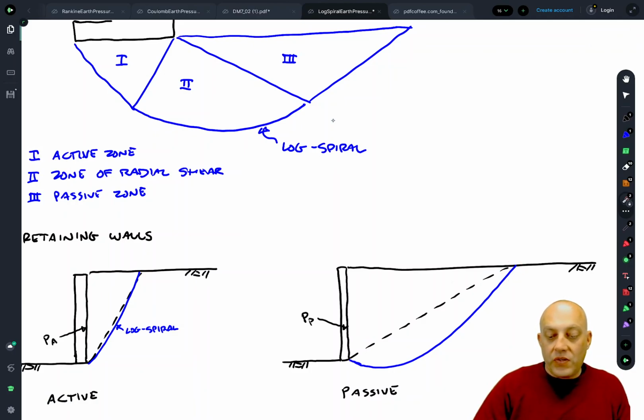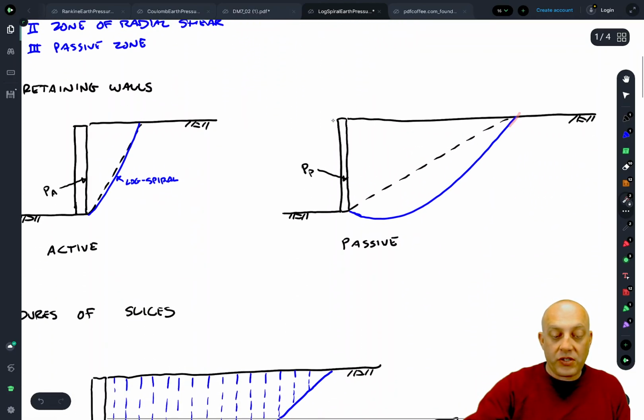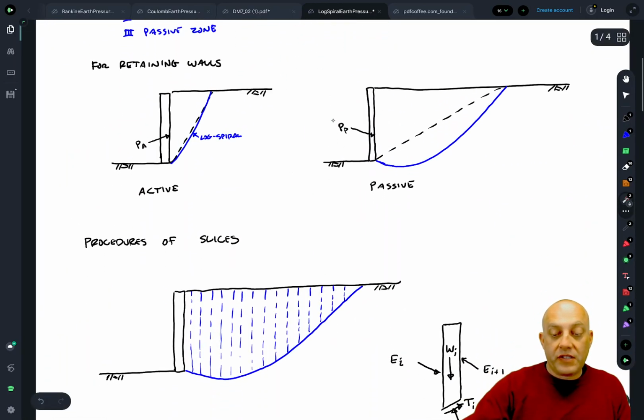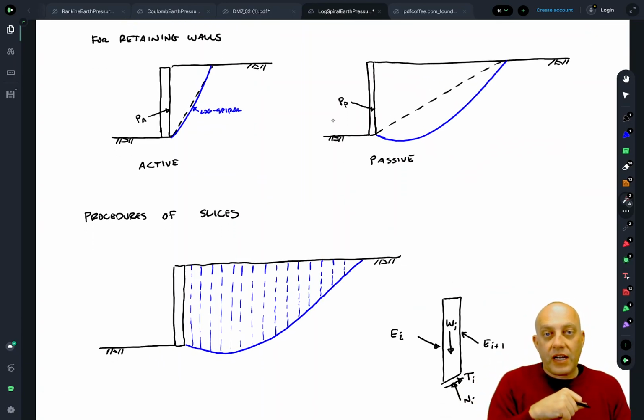But anyway, you see that these failure mechanisms are really quite different, right? This planar failure surface really is the wrong one. And this one will give you a lower passive pressure. So it's a better estimate of passive pressure. Great. So how do we come up with the properties of this surface now and the equilibrium conditions? Well, I'll show you some tables that have earth pressure coefficients summarized. It turns out it's not so easy to just conveniently come up with a simple expression anymore for passive earth pressure, so a lot of the time we pick out values from a table.